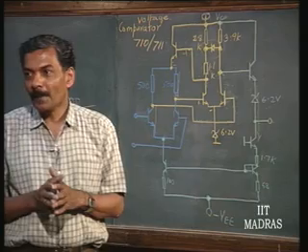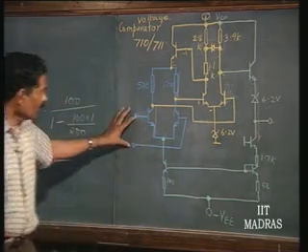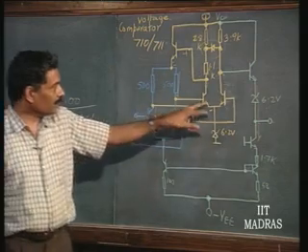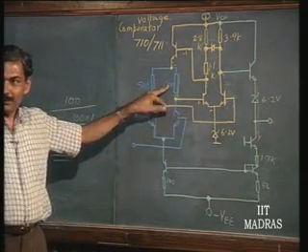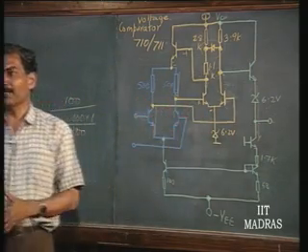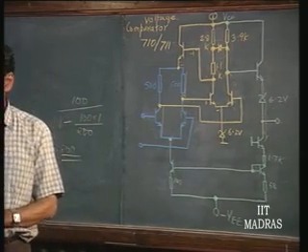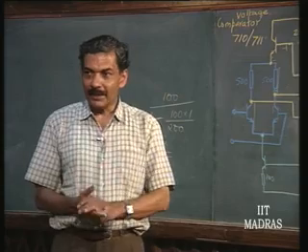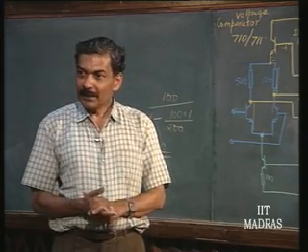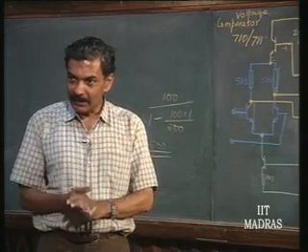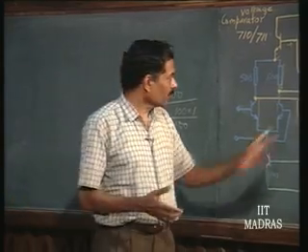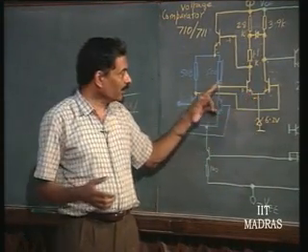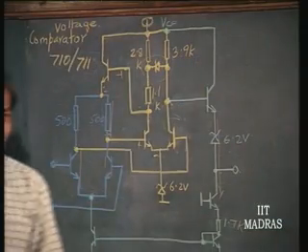Is too small here. Where? Yes, we are not bothered about that. For that stage, second stage. For this stage, input impedance, this is 500 ohms. Okay, so if it is operated at let us say 1 milliampere current or so, re is about 25 ohms, into beta 200, so about 5 kilo ohms. So it is not loading it at all. This input impedance is of the order of 5 kilo ohms also, and it is 500 ohms here. So it is not loading.